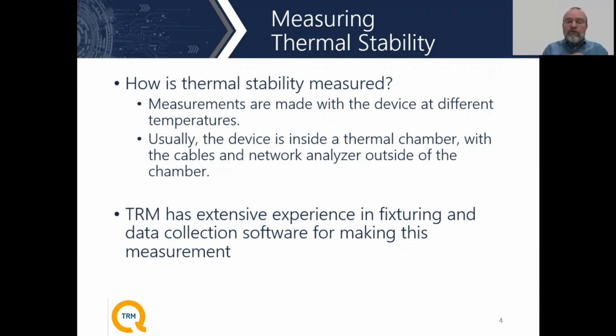So usually what we do here at TRM is we modify thermal chambers to make sure that we can get all of the cabling outside of the chamber or the environment with just having the unit inside the environment. What this leads to is some very, very custom fixturing. I think you have to think this through to really understand what is the device that you're measuring and what isn't the device or the measurement system that you're measuring with.